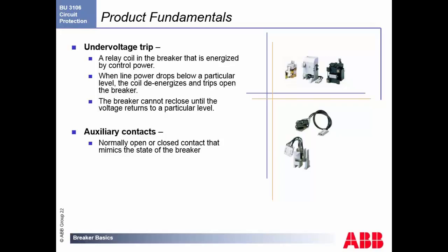is monitoring the voltage that is coming into the unit. Now, as we all know, in the United States, we have typically clean power, but there are plenty of places that are rural that have power drops coming out of the service provider. And this can cause damage. If you have a 480-volt motor and you're starting to see 400 volts on that motor, you're going to really stress the windings of that.